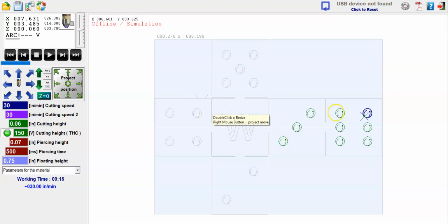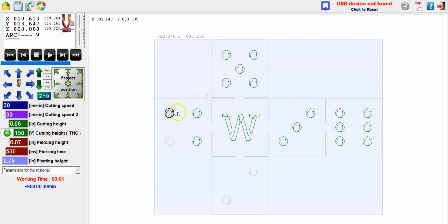Now, let's say we wanted to move around our piece. So once we've made a piece, and we're going to go over that in another video, once we've made our piece, brought it in here, and got it set for cutting, we can actually move around our piece by hitting the forward one path button. That is to say, you'll notice on this screen, this blue icon is going to move. I'm going to keep hitting forward, forward, forward, and it will move through your cut so that, let's say I wanted to start from this point because it missed this point, I can actually hit play. It's going to move the torch over to that point and then cause the system to cut that part out. And then I can just hit stop, or I can let it keep running and cut out the rest of the piece.